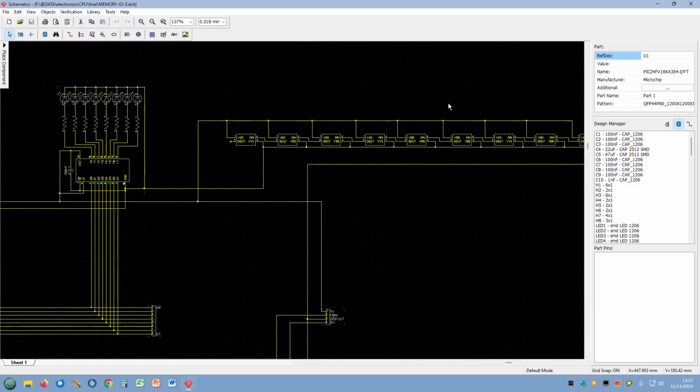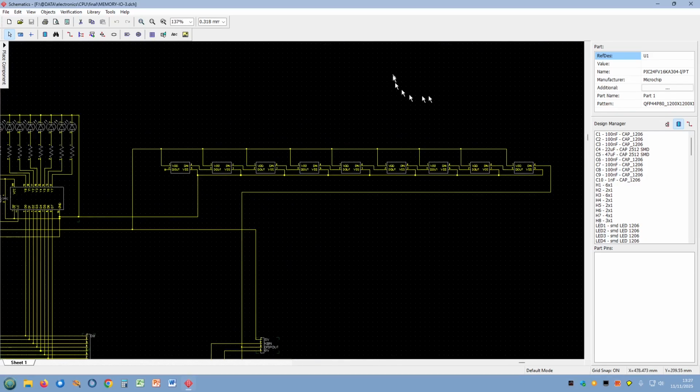So this is the display, which is made out of serially addressable LEDs. So we've got one output here, it's pulsed output. It's one of the pins on the microcontroller. You just send a pulse stream out of here, data in, data out, data in. They're all serially linked up, and you send the data for this LED first of all. It'll come into this LED, and then when the next group of pulses come along, this will get transferred into there, and the new ones will go into there, and they'll gradually work their way along.